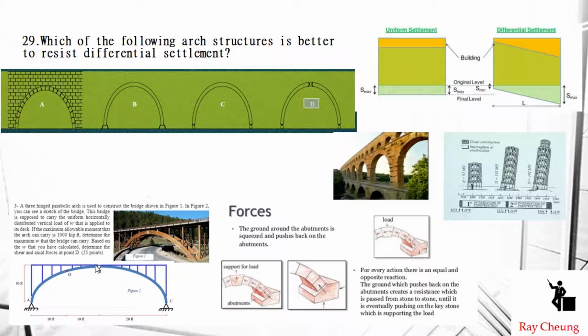This is another one, the bridge. They will use the V-joint type of arch. For example, if the right hand side settles a little bit, it will not affect the whole, and this allows some settlement. This is a so-called V-pin arch.